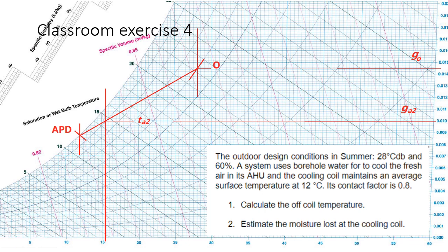Dew point is here. We draw a horizontal line to meet 100% saturation. So you can see for this amount of moisture content, the air at 28 degrees is only 60% saturated. And if we reduce room temperature, it becomes 80% saturation.